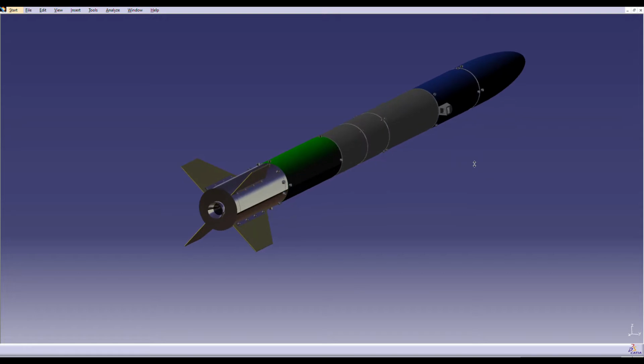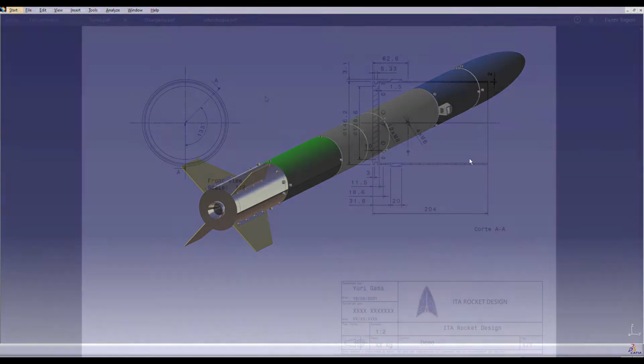This assembly can then be used to make finer simulations with proper mass and inertial measurements, the final geometry of the rocket, and we can also use it to plan manufacturing and integration procedures. And then after that, of course, the first iteration won't be perfect, so we can engage in many kinds of feedback loops with the other subsystems where we can refine our design and go through all these steps multiple times until we get the performance, apogee, and payload capabilities we need.